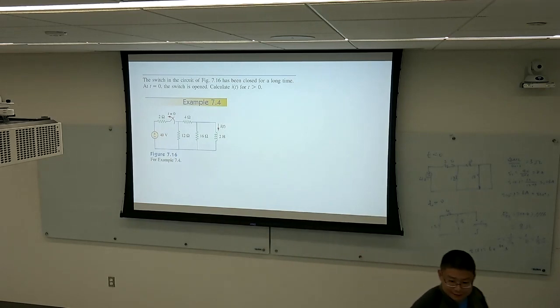To get the equivalent resistance, where do you try to find that? Yes, so these two would be in series, right? These two in series and then this becomes 16. So when the switch is open, this one does not exist. Oh, okay, I can see that. So this is in series and then parallel. Okay, I did that backwards.